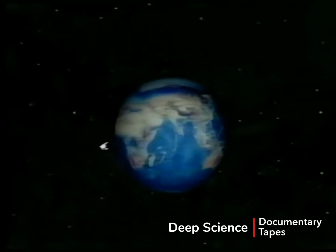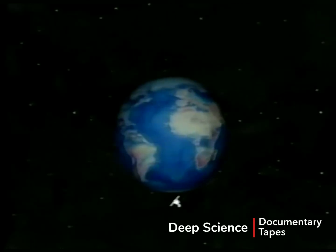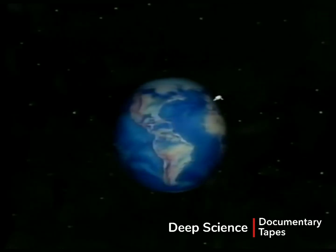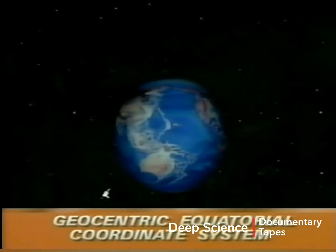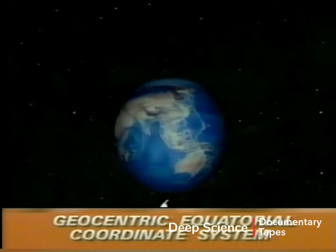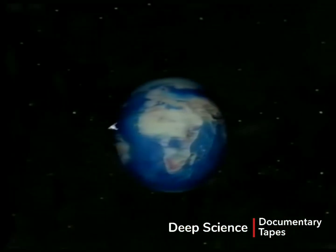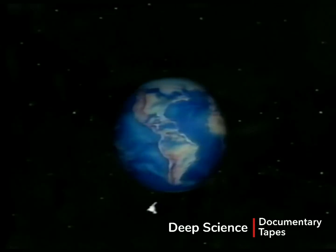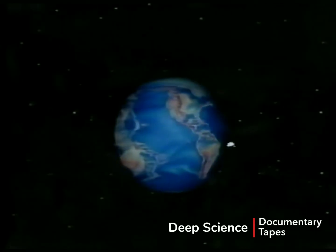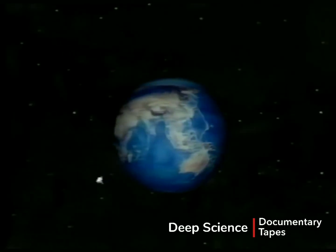When orienting an orbit in space, a three-dimensional coordinate system must be defined. The coordinate system commonly used is the geocentric equatorial coordinate system, which has its origin at the Earth's center. This coordinate system is a non-rotating reference system in which a satellite's orbital plane tends to remain fixed relative to the stars while the Earth turns beneath it.